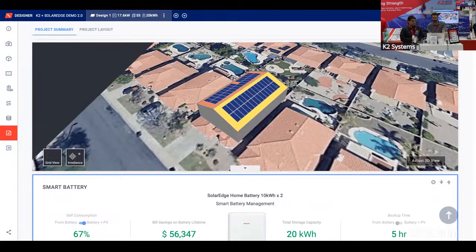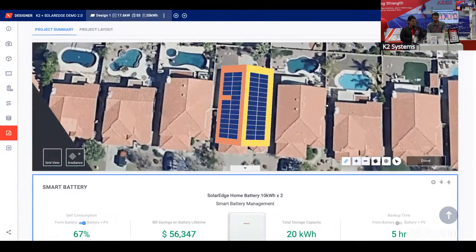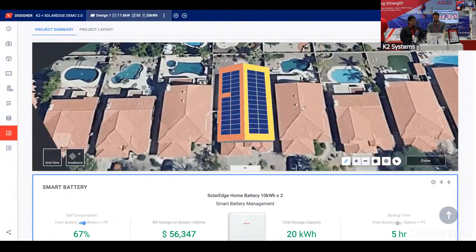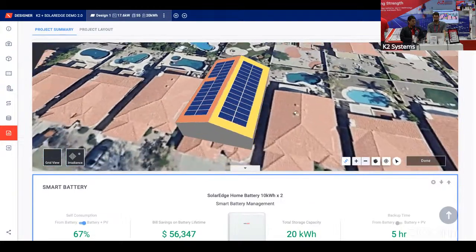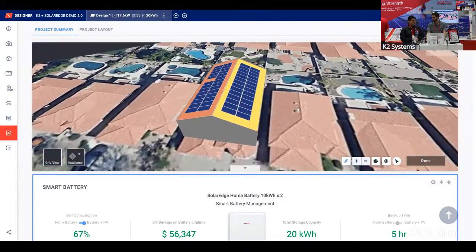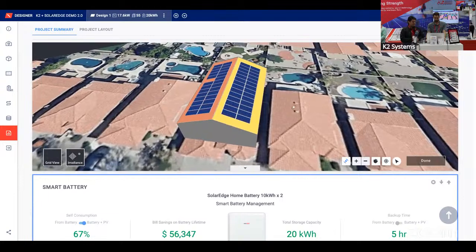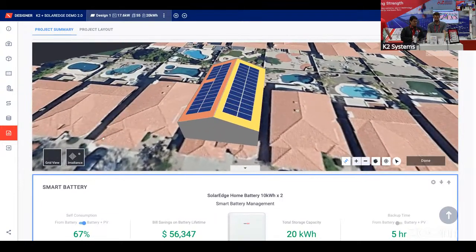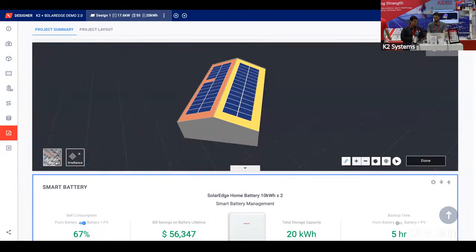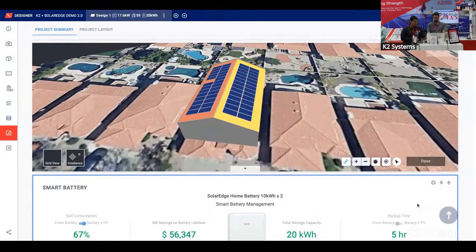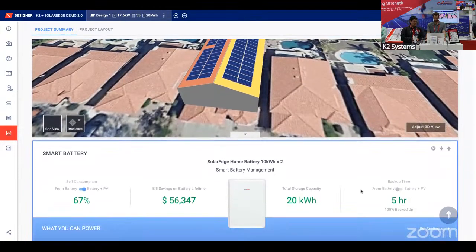So this irradiance tool or button here allows you to see how much irradiance each side gets, and we can adjust this guy here. Let's see if I can use my mouse, right? So we can kind of give it any view here. I'm going to go in a little closer. How's that? Is that okay right there, you think? Yes. Nice. All right. Okay. We can just do the grid view without any of that stuff. But that looks nice. Okay, we'll hit done there.